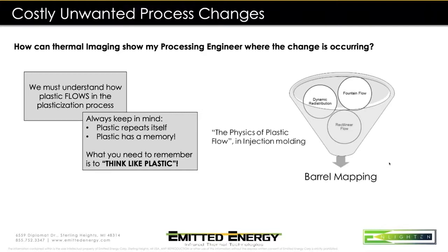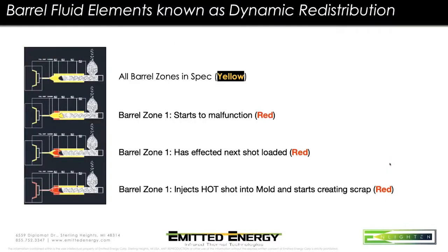Fountain flow: you have to understand that the plastic itself does not push through the mold. What it does is flow out like a fountain, and it goes in between two skins, between your cavity and your core. Depending on what that speed is and how thick that skin is, it will pick up some frictional shear heat as it flows between those two layers. If you get with me later, I'll send you a video that was made by GE that had some colorant put into that.